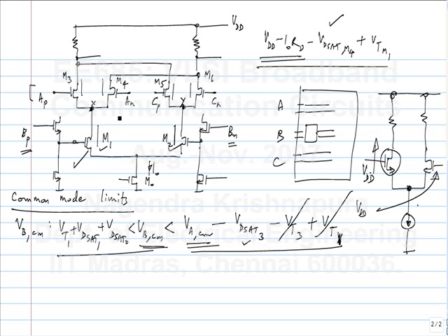By putting these level shifters, we have satisfied this. In fact, we have done more than this. What is the actual VBCM in this case? This VBCM refers to the common mode voltage at this point, which is what we calculated. I am saying the common mode voltage of this and this are the same. What is the common mode voltage here? Minus VT minus VD sat. All we need is a difference of VD sat, but we have a difference of VGS. We have met this condition by a lot of margin, so in this case that won't happen.